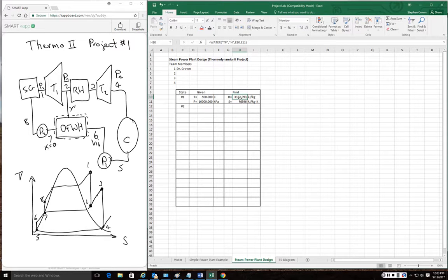let's do y prime h2 plus 1 minus y prime h6 equals h7. And there's nothing multiplying h7 except a 1. It's 100% of the flow again at h7. And then finally I can solve for y prime.